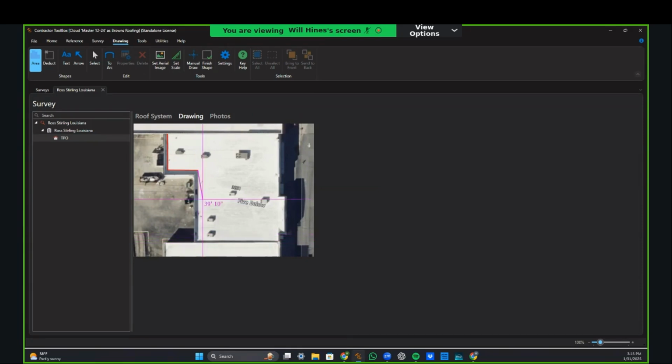Also worth noting, currently I have it set to where my controls are keybound. So for me, holding shift locks on to previous points. As you can see, it's locking me onto the point that I drew here. And now it's also locking me onto the one that I drew here. You can see the crosshair changes color, versus when I'm here, it changes to a blue. That's showing that lock on point. Also, if you hold control, that allows you to snap to 90 degrees and have a perfectly straight line up or down.